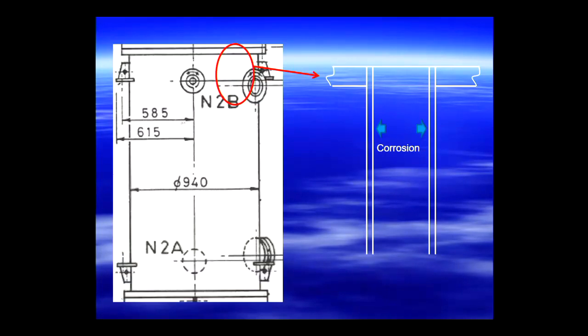The surface of the boiling liquid is at about 100 millimetres down from the top of that tube. And because that is rather violent, it abrades the material at about that point. So all of the rest of the exchanger was perfectly good, except for this little tiny region about 3 or 4 millimetres wide, where the level was, and that's where they all used to get eaten out.